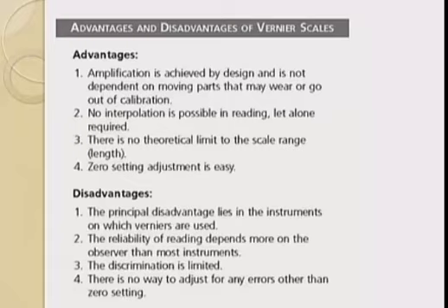The disadvantages. The principal disadvantage lies in the instruments on which the verniers are used. The reliability of reading depends more on the observer than most instruments. The discrimination is limited, and there is no way to adjust for any errors other than zero setting.